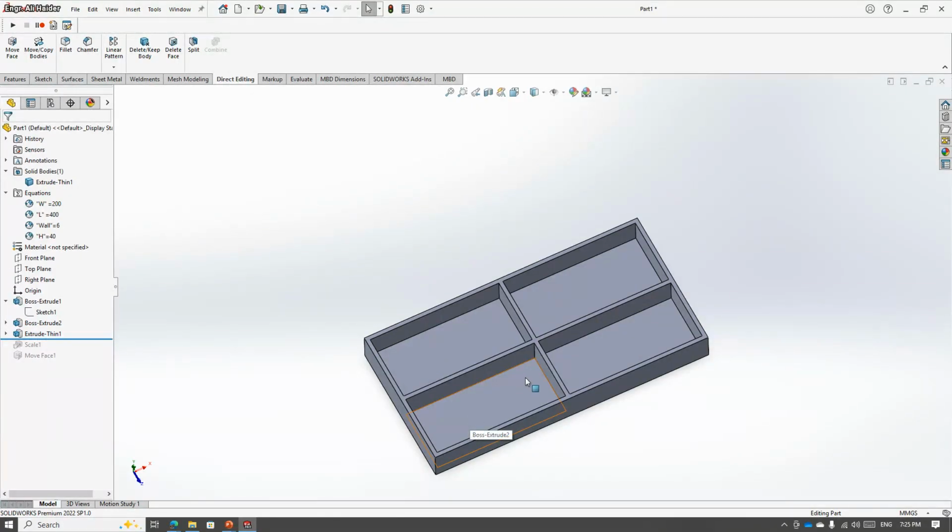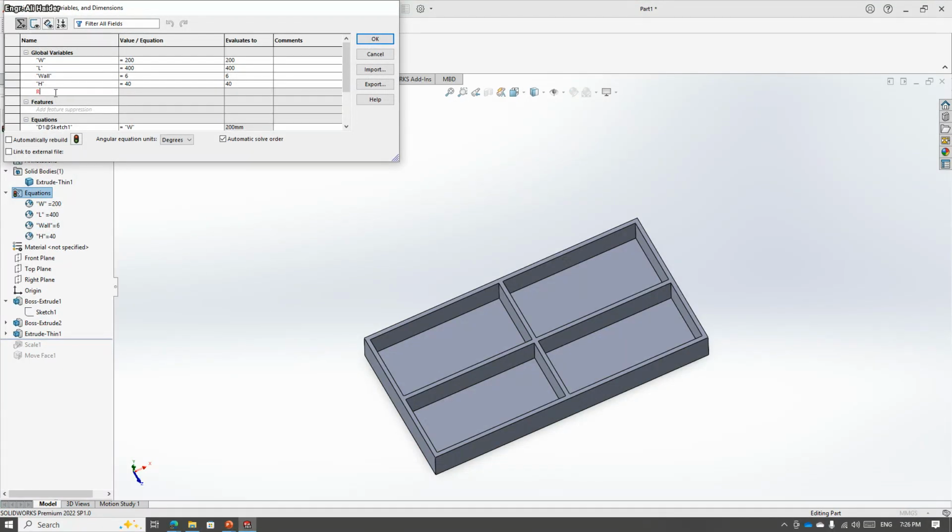So however complex your design is, once you have those equations here for the major dimensions that you think in future we might have to change, you should use them with the help of the equations. At the very first stage, you should provide the width, the length, heights. Maybe you should provide the rib thickness. You can just go to the managed equations. You can type in here rib thickness. You can give them the value of 1 mm and click on OK.